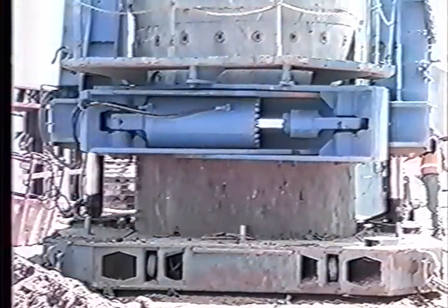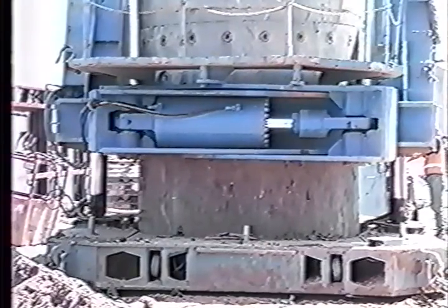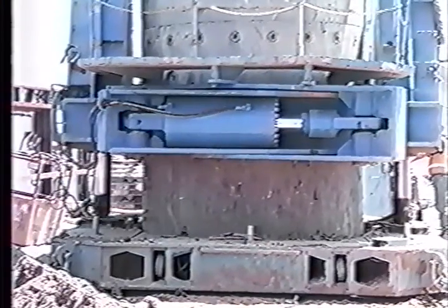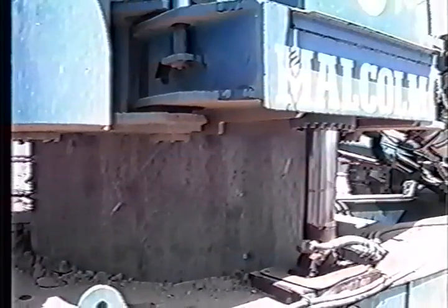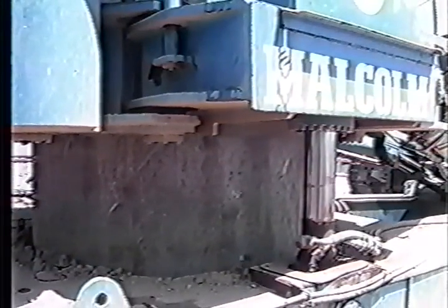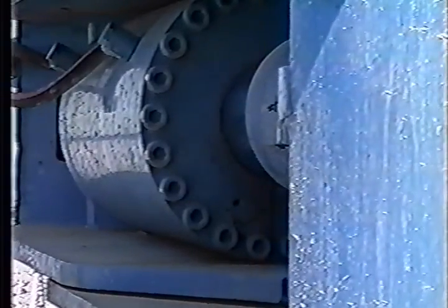The Leffer 2.5-meter hydraulic casing oscillator was used to drill holes 6.5 feet to 8 feet in diameter and up to 125 feet deep. The oscillator operates by rotating 20 degrees in alternating directions while using powerful hydraulic jacks. This awesome machine continuously oscillates, twisting and pushing the casing steadily down into the ground.